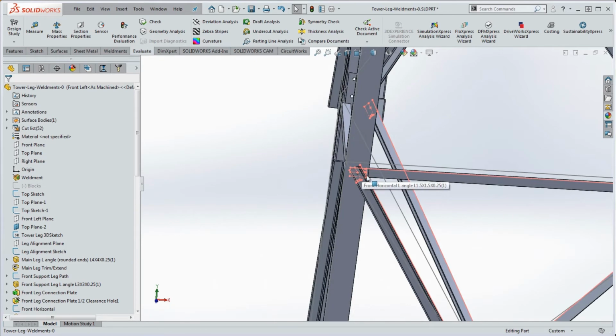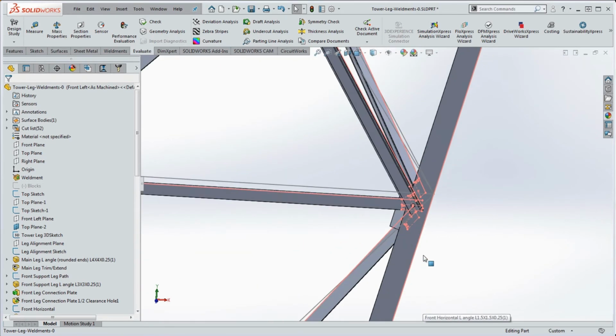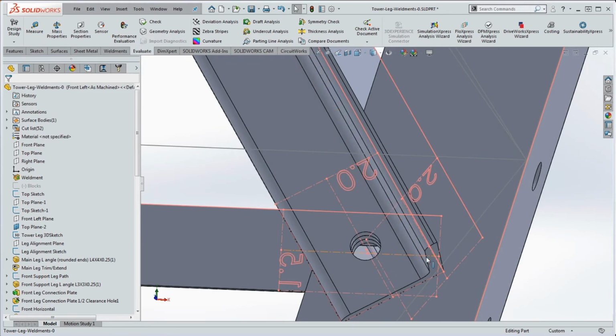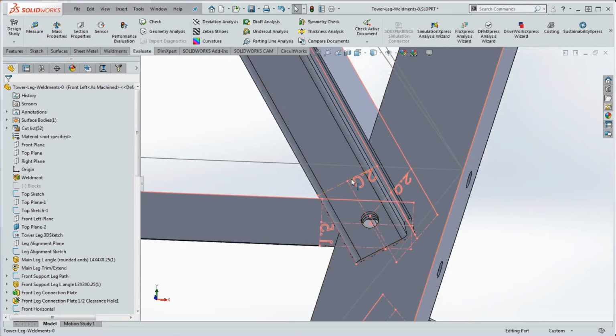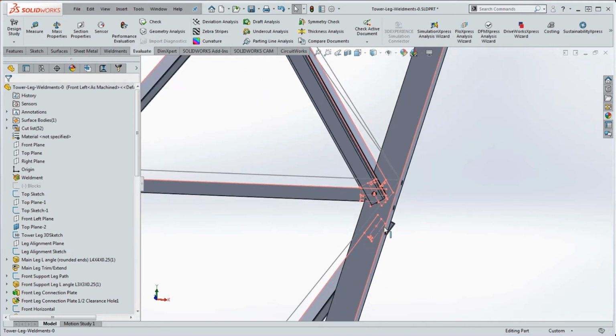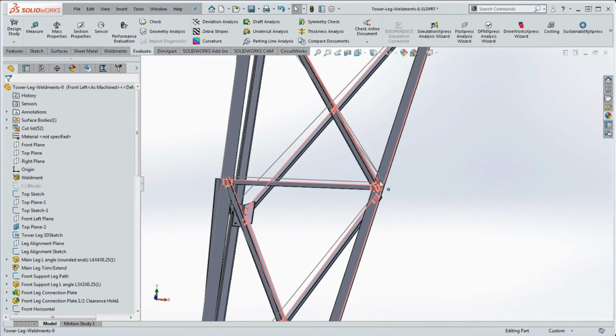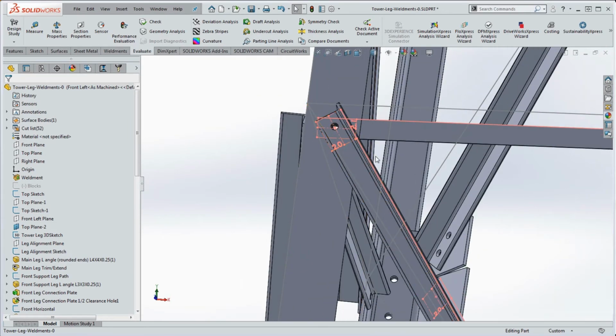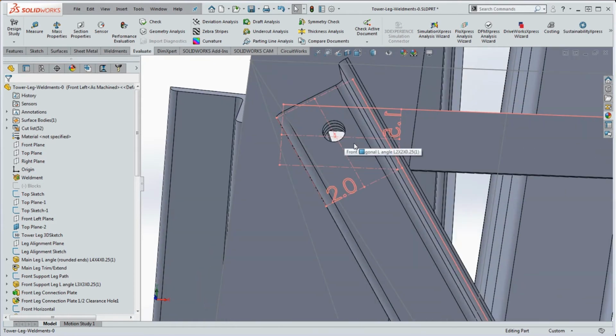These pink sketches define where the different structural members and their path segments come together. So each path segment in here comes together like a barbell in a way, where you have a sketch block in the very end of that, on both ends of it. So this 2-inch diagonal up here, it's got a sketch block at the bottom, it's got a sketch block on top, and then it's connected by a structural member path segment. So that's your path segment, and you're going to get your structural member to go right on top of that path segment.